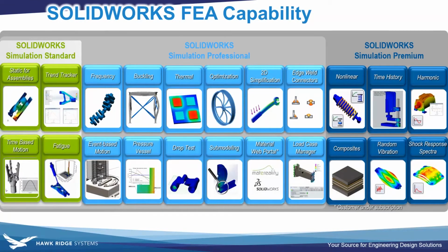So the nonlinear stress analysis allows you to put in the material models and the contact definition that you would need for any kind of manufacturing problem like this, and it also has the contact detection abilities beyond just a simple static study. But even the nonlinear study is going to have some limitations. So let's try to see how far we could get with SOLIDWORKS simulation.